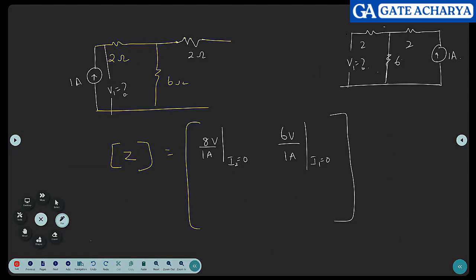Just one current source, finding the voltage. That's all. Always remember, through this element no current is flowing, so the potential drop across this is 0. Whatever voltage is here, the same voltage will come here. How about next here?